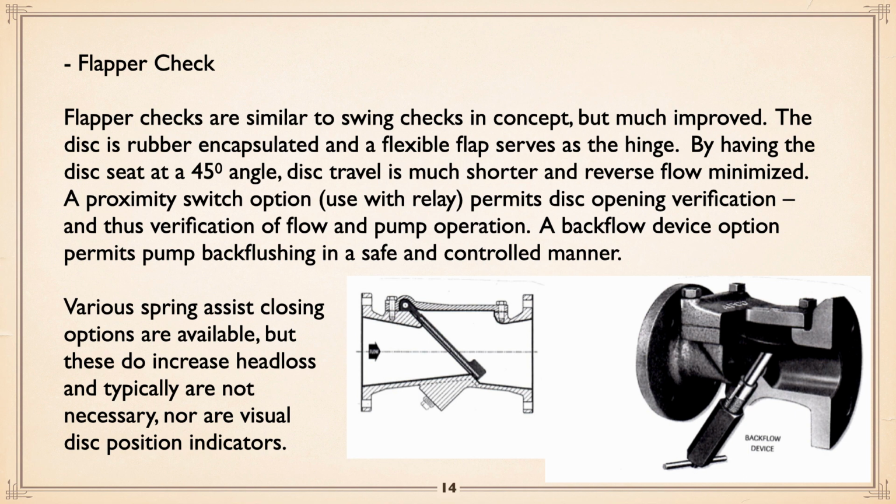Oddly enough, and this became an issue at one time and some research was done, the motor is not the problem. The motor can only develop locked rotor torque and locked rotor inrush. So although it may take a little longer than normal startup, the amperage will not be any higher, and the torque any higher, than what it normally is when you start the pump. So they really aren't a problem with the coupling or the motor.